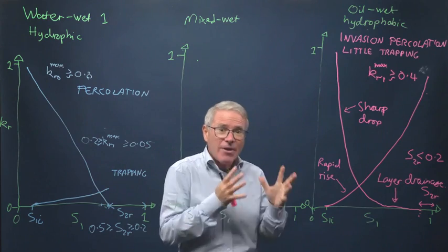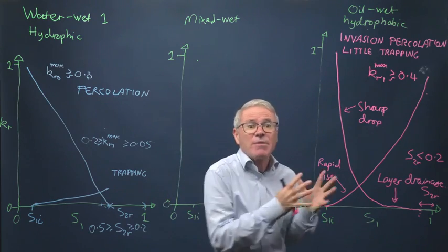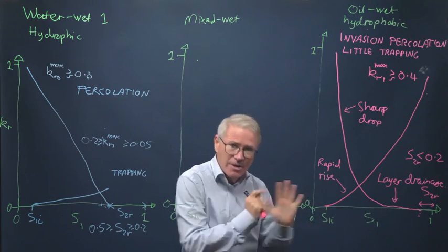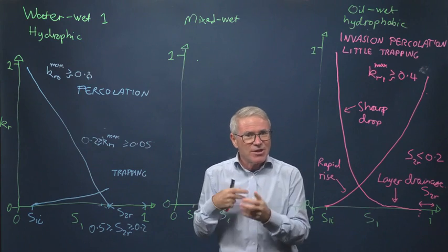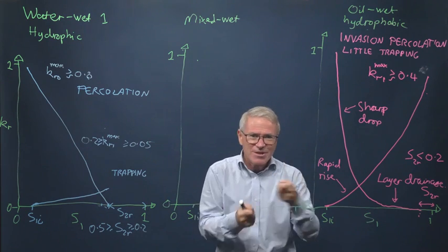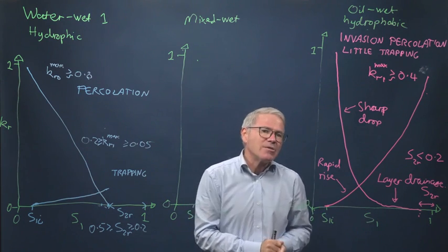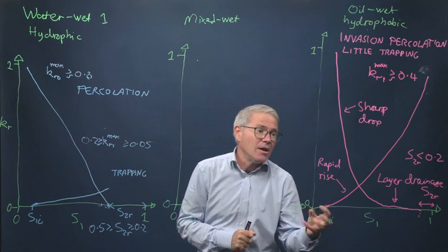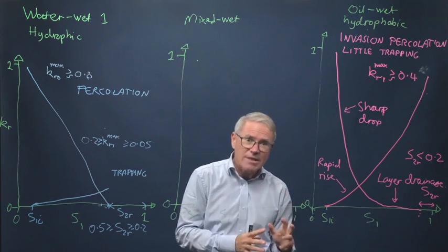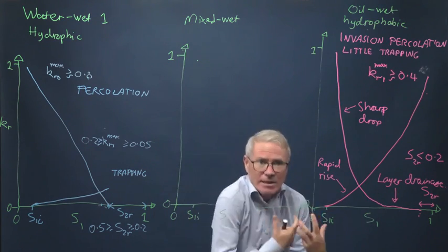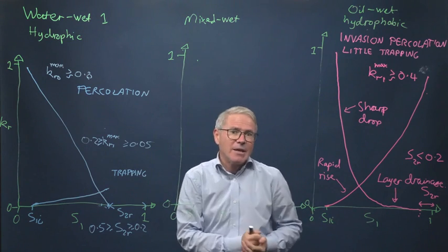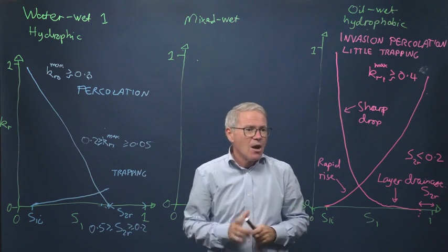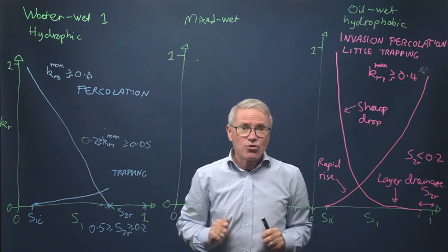In theory, if I keep pumping and pumping for months, okay? In theory. But in practice, if I'm just going to inject a little bit of water or hope that it pushes its way out, I'm going to actually retain a lot of phase 2 because it's the wetting phase. It likes the surface. It likes being in the porous medium. It doesn't like coming out, okay? Okay, so that's those two extremes.